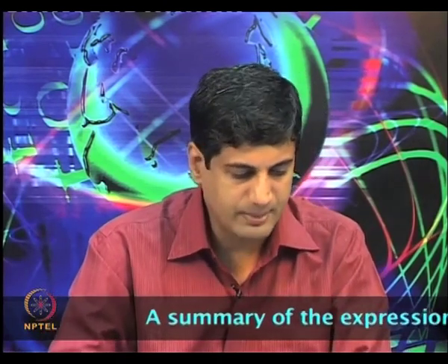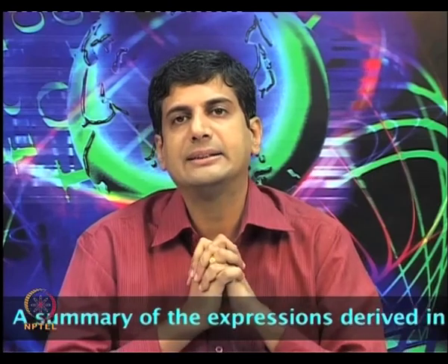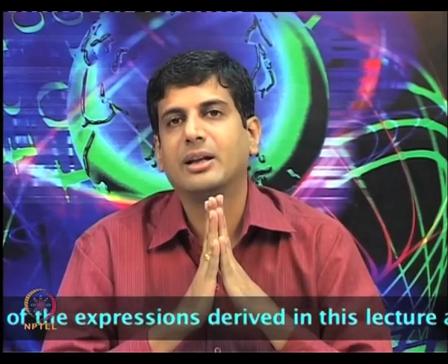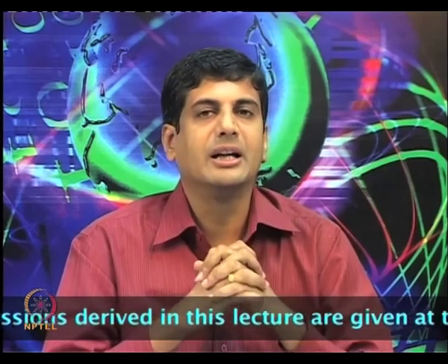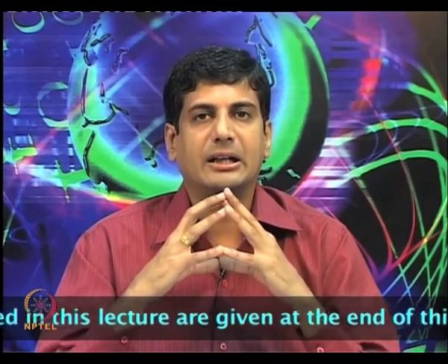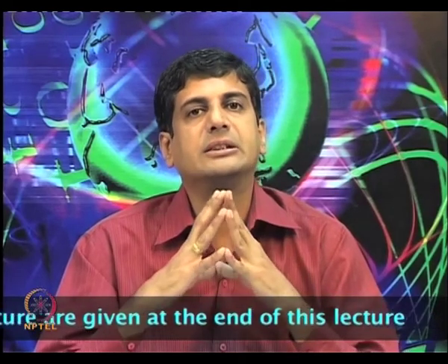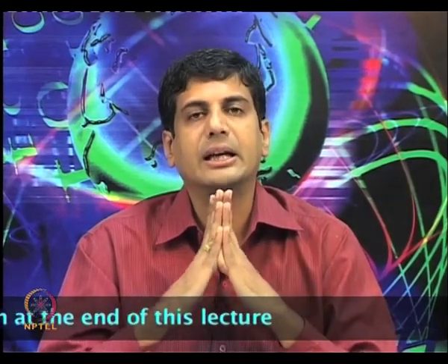To summarize this particular lecture, what we have done is finally obtained the equations of the synchronous machine in the dq frame of reference. And the equations are neat in the sense that they are not functions of theta. If the speed of a machine is constant, that is d theta by dt is constant, the flux differential equations are linear time invariant equations. Of course, if speed is not constant, which in general it need not be, you have a coupling between the mechanical equations and the flux differential equations. That coupling is non-linear.